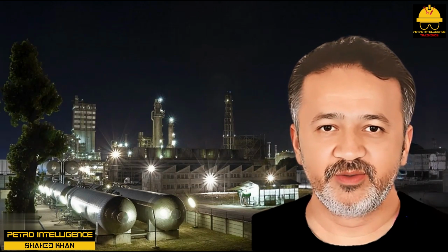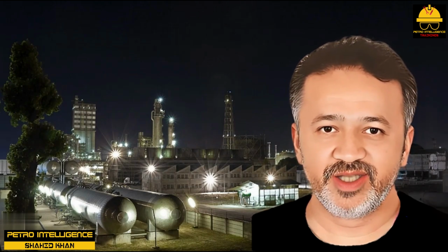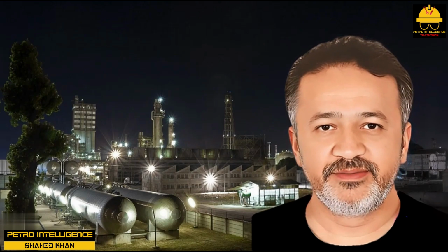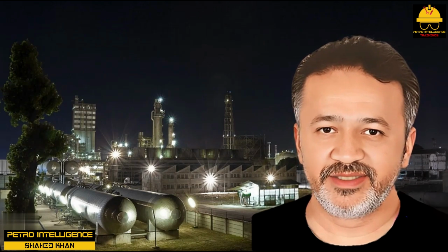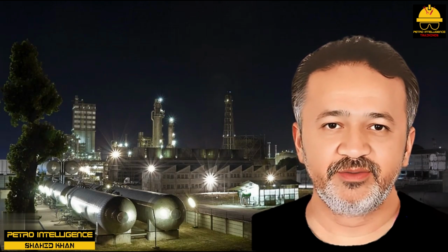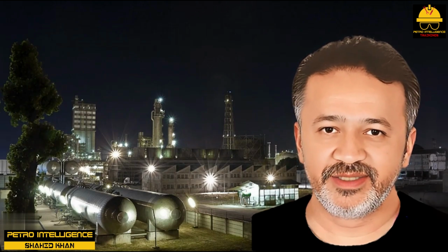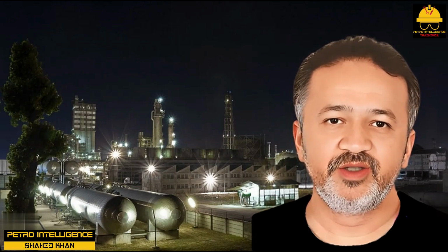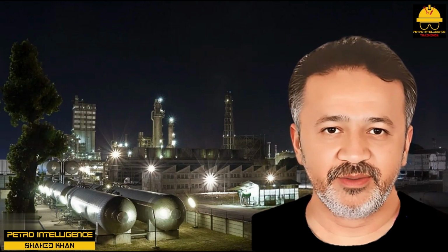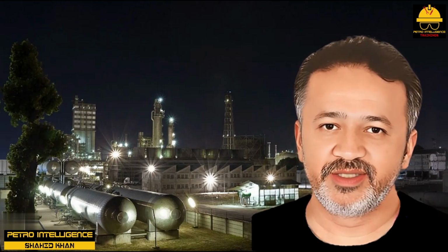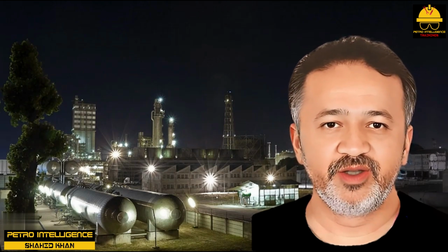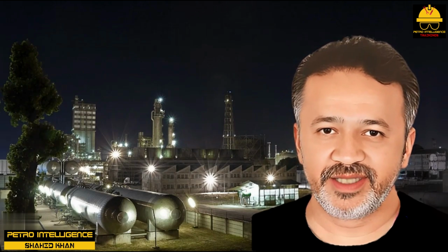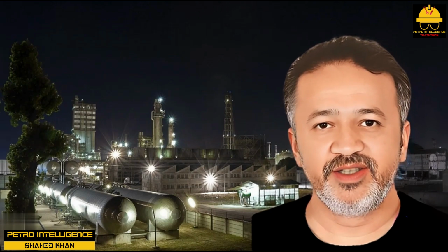As we try to desulfurize diesel oil, some small fraction of the hydrocarbon will turn to coke. The coke covers a tiny portion of the surface area of the catalyst. This slows down the rate of reaction between the hydrogen and sulfur molecules, converting to H2S in the diesel oil. The sulfur content of the diesel product goes above spec. To reduce the sulfur content of the diesel below spec, the operator raises the temperature of the reactor. This makes the reaction go faster, which is good.